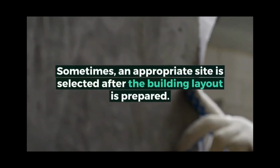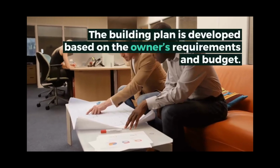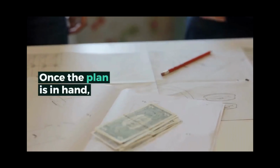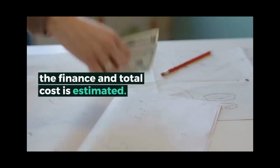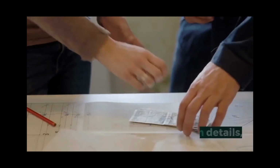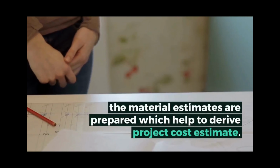Sometimes, an appropriate site is selected after the building layout is prepared. The building plan is developed based on the owner's requirements and budget. Once the plan is in hand, the finance and total cost is estimated. The structural design details and the material estimates are prepared, which help to derive the project cost estimate.